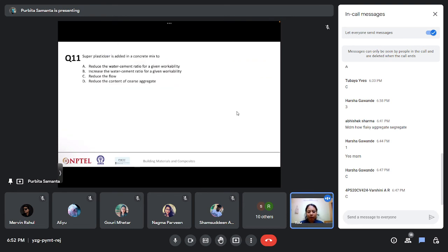Now coming to our 11th question, which is: superplasticizer is added in concrete mix to, and you have again four options: reduce the water cement ratio, increase the water cement ratio, reduce the flow, and reduce the content of coarse aggregate. I know you have learned about plasticizers. Related to plasticizers, I'll give you the basic difference between plasticizer and superplasticizer. I think from the name super only, you are all able to understand.